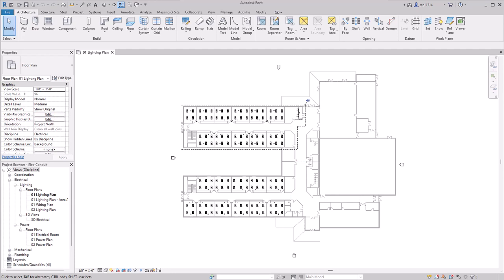In this video, we're going to take a look at how we can add electrical conduits to an Autodesk Revit project. Conduits are basically pipes that we're going to run our wiring through, and similar to plumbing, I want to make sure that I limit the angles that the pipes can be created at. If we're using conduits with fittings, we can't just draw them at any angle. Our fittings are available at certain angles. So that's the first thing that we'll do.